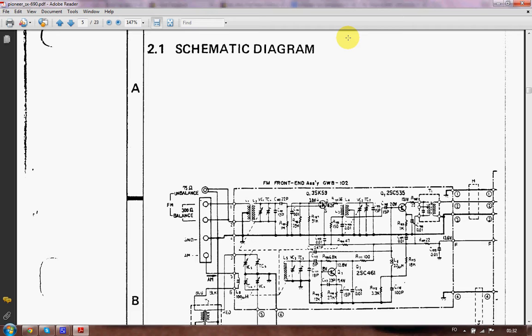That's the input signal from the FM or AM part of your unit going to your amplifier circuit. These are all signals, and these come in 2 channels if you have stereo. They enter the amplifier in 2 channels, and they exit the amplifier circuit in 2 channels. There is no way that an amplifier can produce stereo. It must be sourced with stereo. Otherwise, it cannot relay a stereo signal to the speakers.